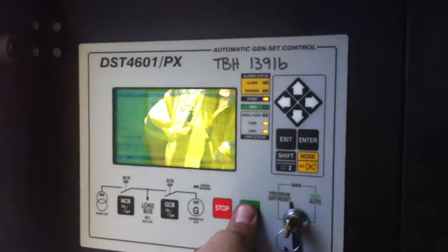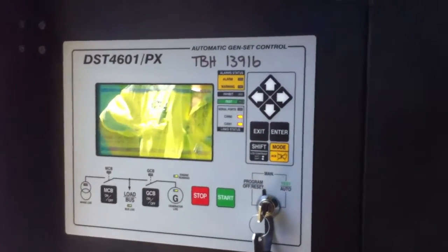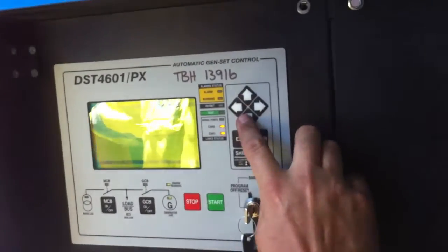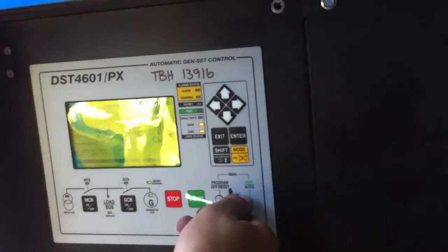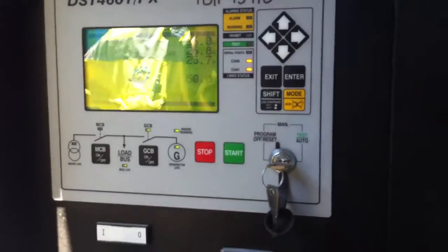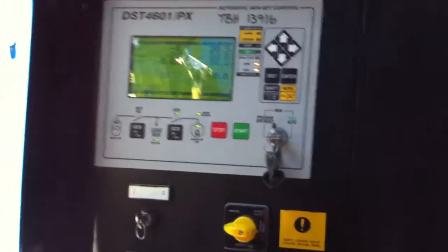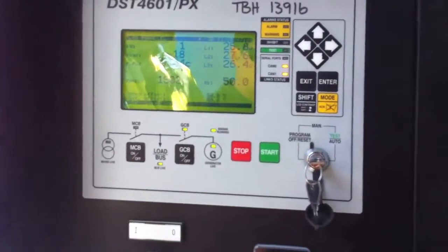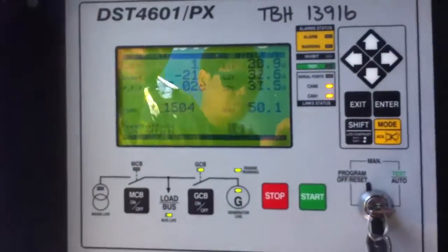Okay, we need to activate the second generator. So we start it up in manual. Get up to speed. And then we put it in automatic. The circuit breaker shall switch on. The unit is now synchronized. That should shut down. So basically now there is no load. The second unit, which is this one, should shut down. It'll wait for a while before it senses that there's no load. At the moment it's in load sharing operation.